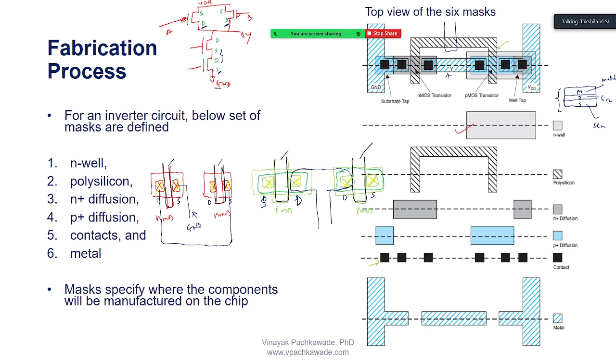So nowadays in the technologies, because of some technological advantage, this metal is not deposited on the oxide, rather a semiconductor called polysilicon, crystalline polysilicon. It's just like silicon, but they are calling it polysilicon. And that semiconductor is just silicon, but it is heavily doped, so it acts as a good conductor.